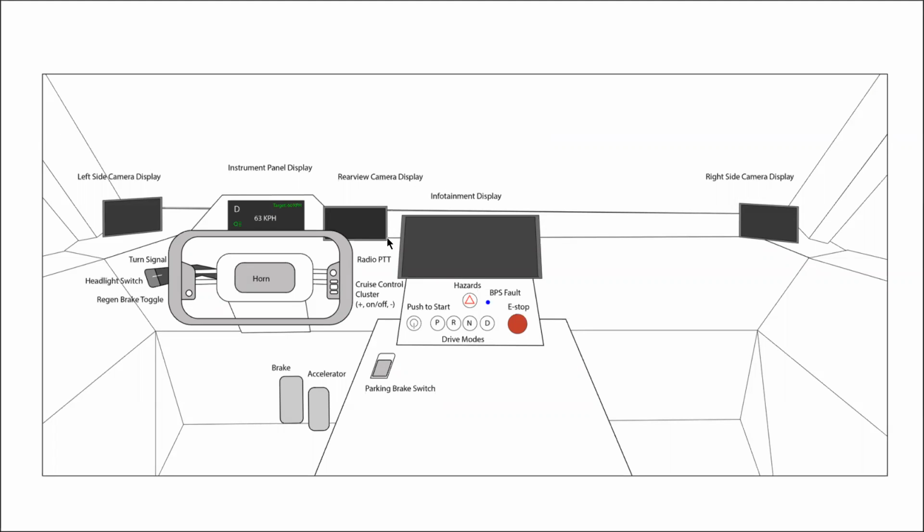The key areas that driver controls deals with are the buttons here on the center console. So you have hazards, park, reverse, neutral, drive, as well as on-off. The steering wheel: you have all of the inputs that you're getting from your steering stalk, as well as the buttons on the wheel itself. And then you have the brake and accelerator. The angles that these make, as well as the angles steering makes, all of those are inputs into our driver controls.